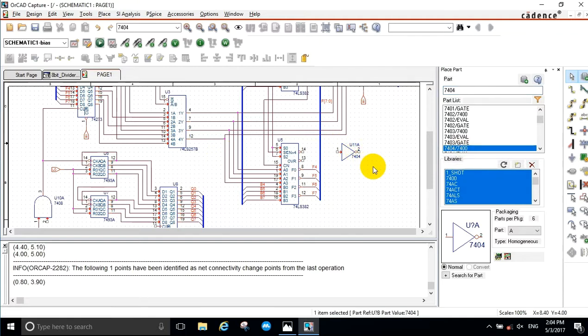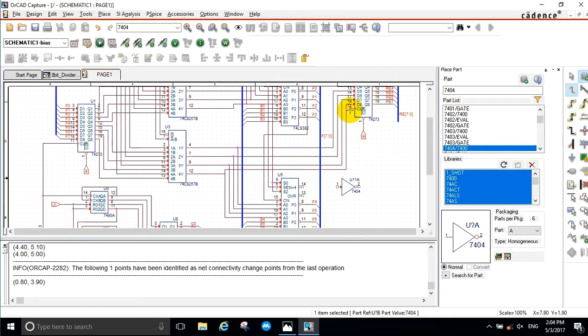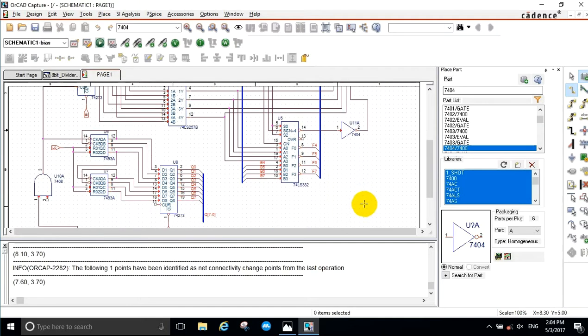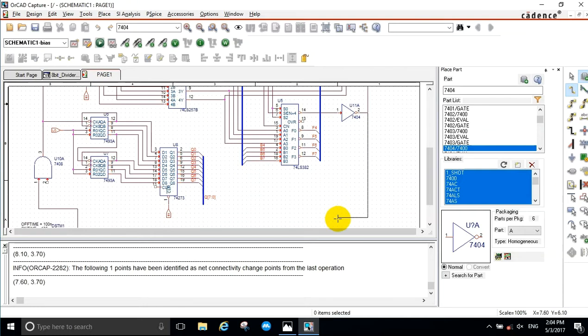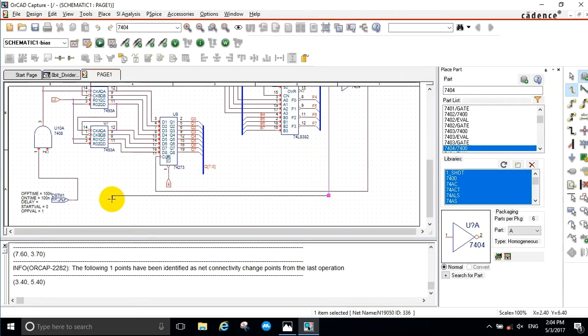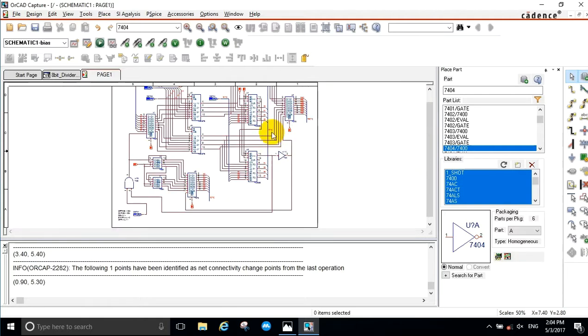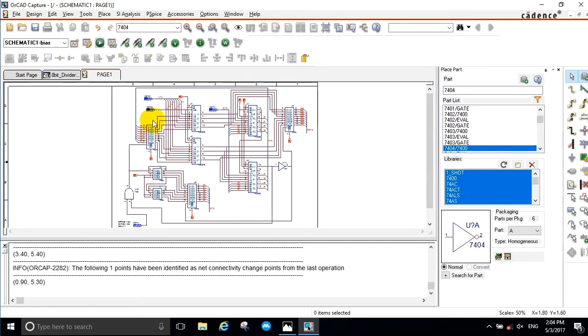The carry out for this ALU will be inverted. So when the output is greater than 1, and the remainder is greater than the divisor, the clock will stop and send the output to the register and keep track of the result. This will also serve as the second input to the AND gate to determine when to stop the clock.